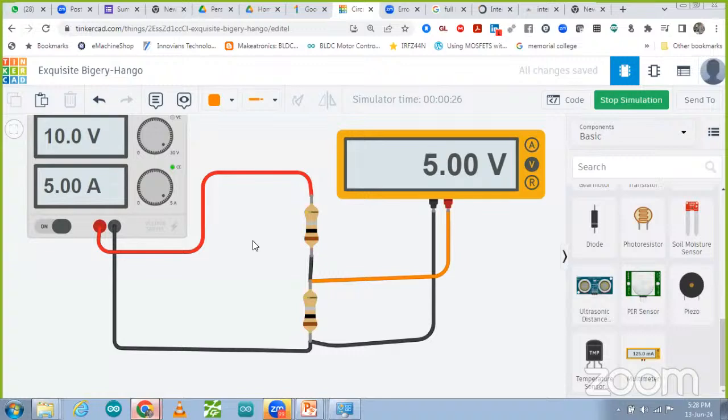So the same thing is happening over here. This resistance value is very small, it means high current flows in the circuitry. So that is 5 ampere current flowing. So if more current than the battery's capacity flows in the circuit, then what is going to happen is that your supply voltage will drop. If your voltage drops, then based on this voltage you are going to get the output voltage.